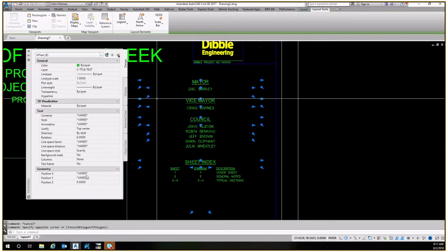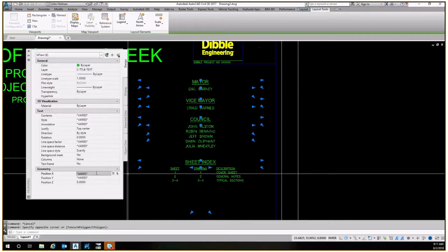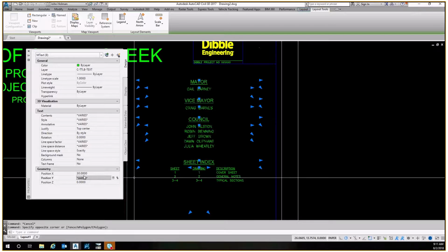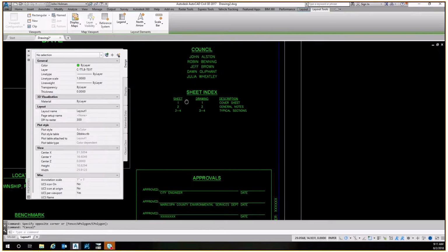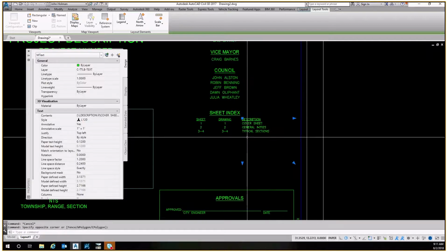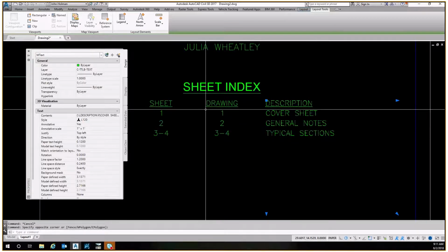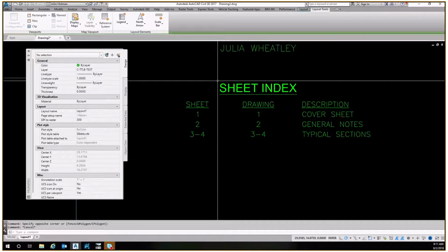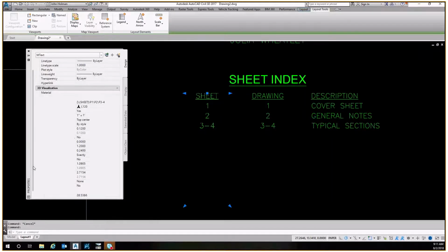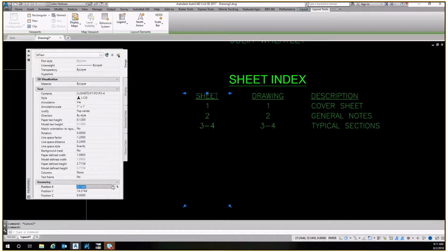Let's go ahead and set all these to position X, and we'll key in 30 for all of those, and that shifts all of them so that they are in a line and have an X position of 30. The sheet and description text boxes here are not in line with those other ones. So we're just going to make these at reasonable positions as well, because I bet the X positions are just odd numbers. This is pretty close to 28.5. Let's make that 28.5.